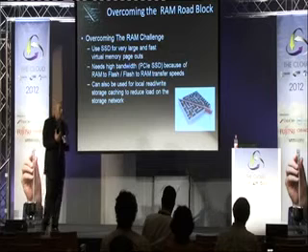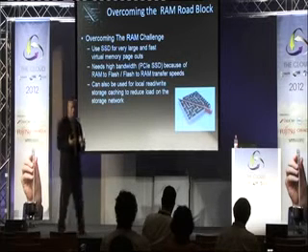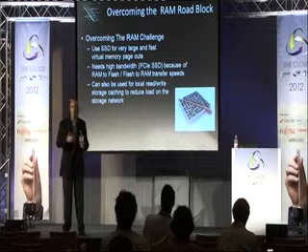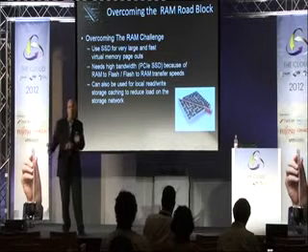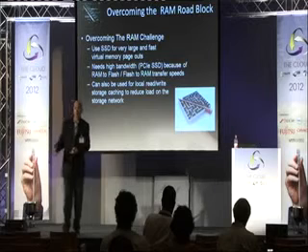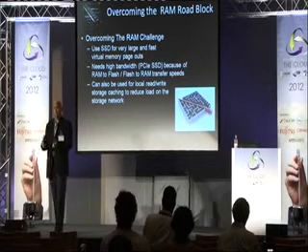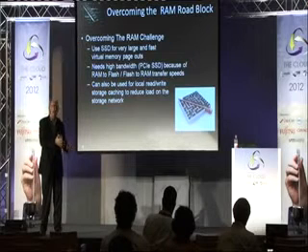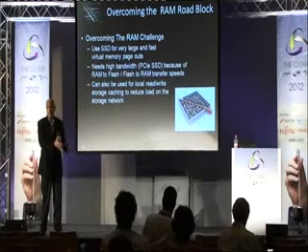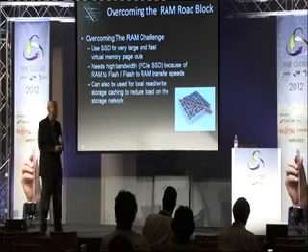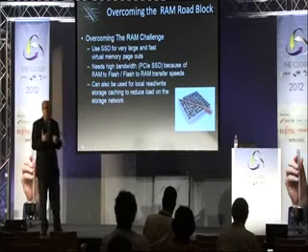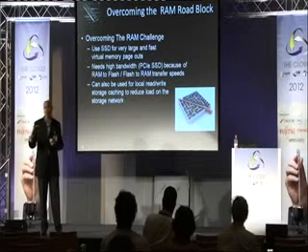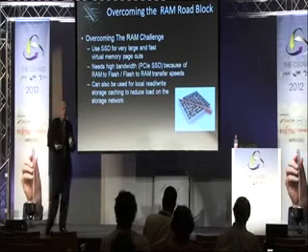And if you think about how you normally use solid state, you use solid state to accelerate a hard drive. So what you're comparing it to is essentially a very slow piece of mechanical equipment. Now, if we're using it to augment RAM, the thing I have to compare to is a very, very fast RAM DIMM. So the performance really became an issue. And it wasn't so much the performance of the flash memory itself, it was the performance of the interface.